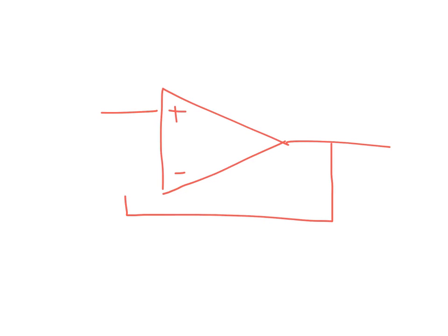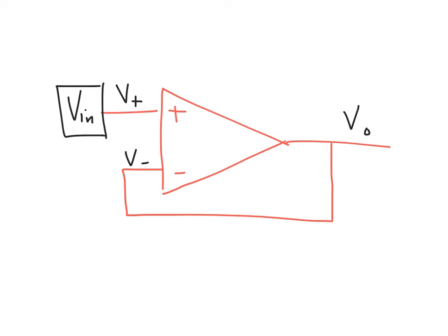The last thing we talked about is one of the basic operations of the operational amplifier. We have the minus terminal of the input connected with the output voltage. This is VO, this is V plus, this is V minus, and at this point the voltage is Vn. We said this is called the unity buffer, with the relation at the end that V out will be Vn.